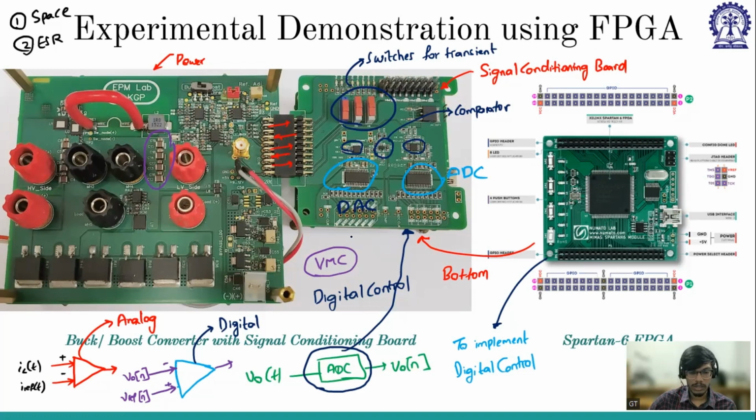Last question, sir. Is there any difference in ESR between the through-hole capacitor and this SMD? Yes. Again, SMD has less area. Less area means again less path, so less resistance in the path. And if you consider through hole, then those exposed pads will have a higher inductance effect, all those things. So that's why for high frequency we always go for SMD, because that exposed path is again parasitic, so we also don't want that. This trace length also has some parasitic, less, but it will still have some finite parasitic.